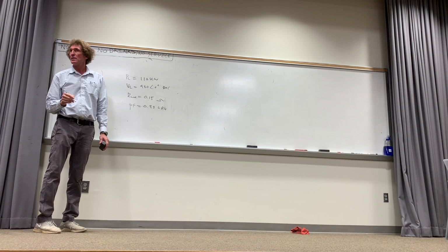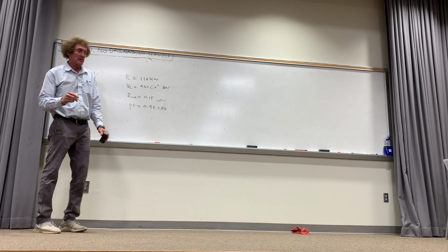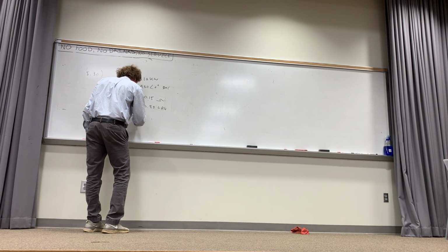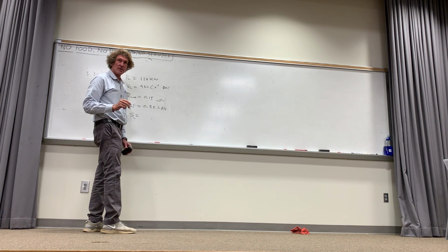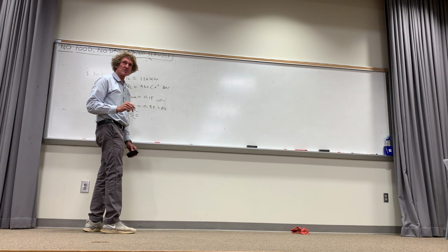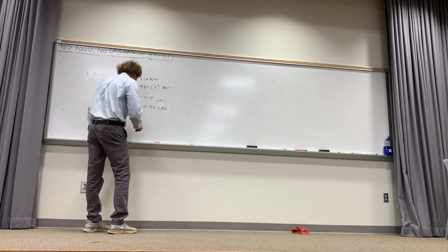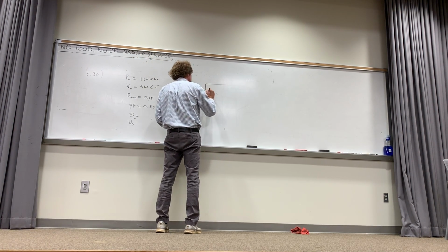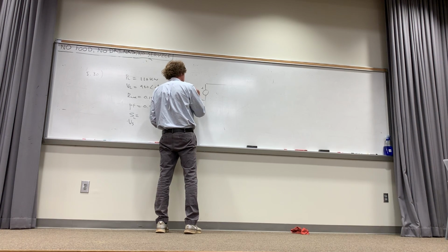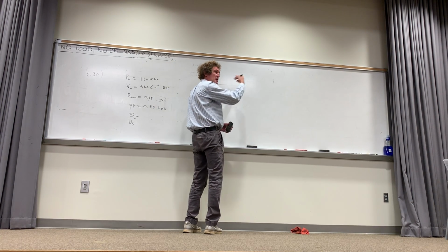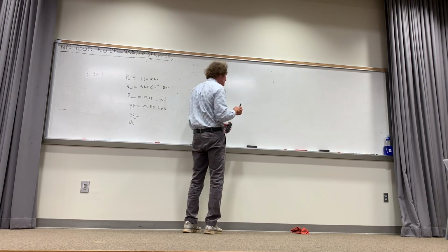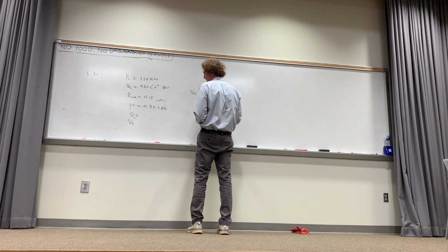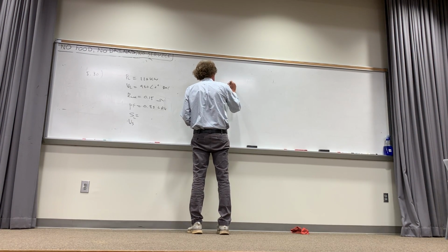The problem is about complex power. All right, they want S, sure. They want S complex for the whole circuit. Anything else? Voltage at the source? All right, let me draw this for you. What it's saying is there's some source voltage at the power company's end. This source voltage has a line in front of it before it feeds the load, and the line has a resistance of 0.15 ohms.